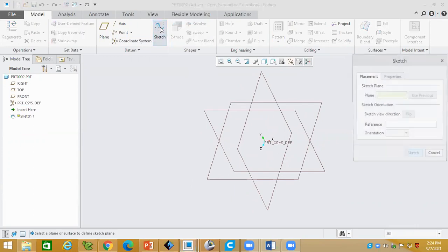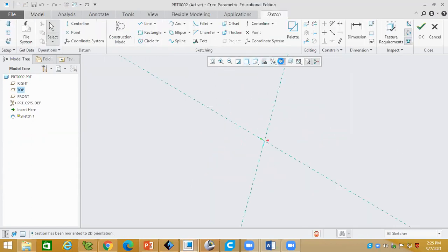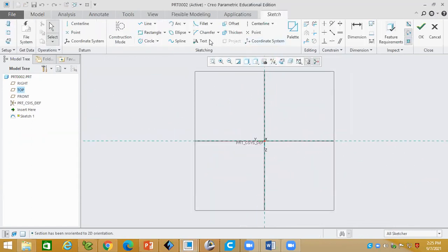Suppose I'm going to make a sphere. When I'm converting a sphere, you can see how it will look. To make a sphere, first we go to the sketcher, and we have to create one semicircle. When the semicircle is revolved about the center axis, we get the sphere. That is the procedure to make a sphere in the CAD model.